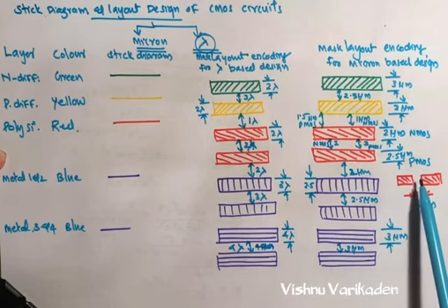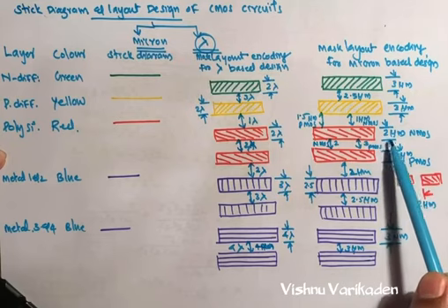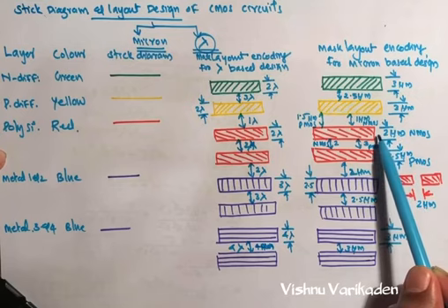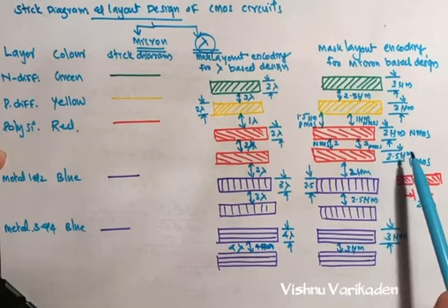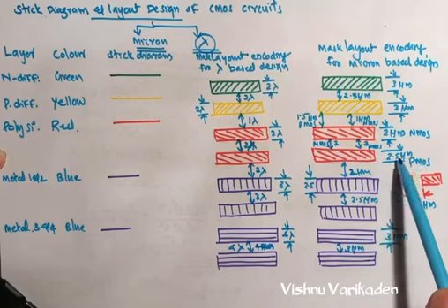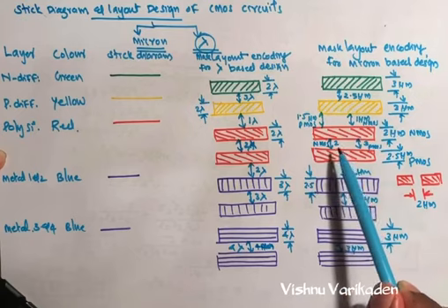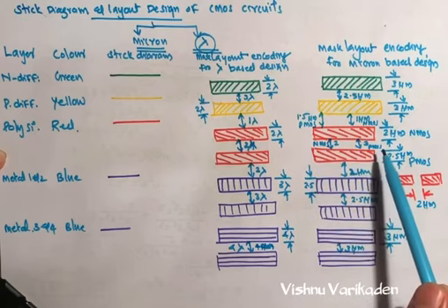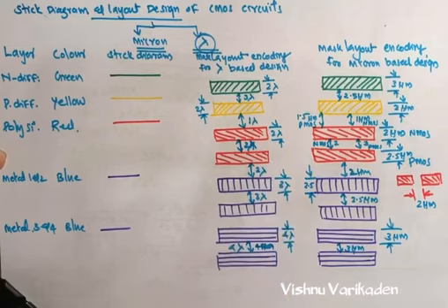Also the distance between two polysilicon is 2 micrometer. Also for the thickness of polysilicon, for NMOS is 2 micrometer and for PMOS is 2.5 micrometer. So there is some variation for NMOS and PMOS in micron based design rule, but lambda it's exactly the same values.